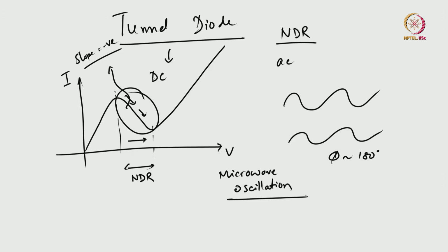The way you get this kind of device IV characteristic is that you use a very highly doped p-type material and a very highly doped n-type material, a p-n junction where both sides are very highly doped. In that case, you can expect to see a tunnel diode. How does it work? If you recall, with a very highly doped n-type layer, how will the band diagram look?